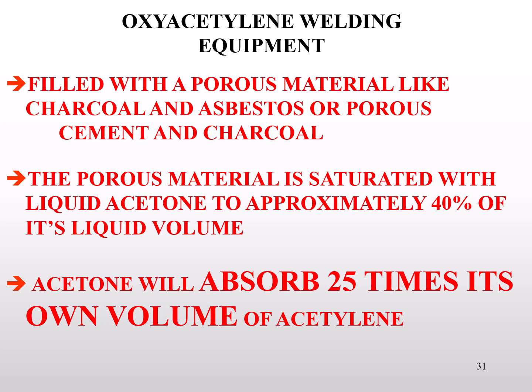The porous material stops the liquid from being able to splosh in the bottle. It would be much like buying a new Coke and shaking it. As soon as you open it, you're going to spray Coke everywhere. Well, the acetylene bottle's porous interior stops a lot of fluid movement, which keeps the fluid calm and keeps the gas suspended in the liquid solution.